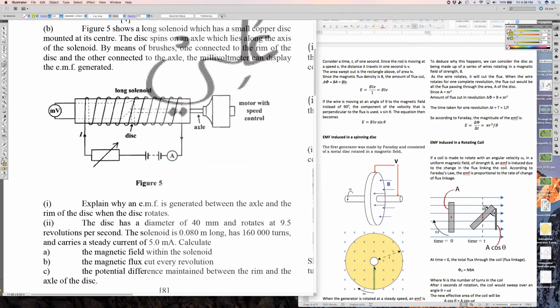This is an interesting question though. Somebody could argue and say, well, sir, this disk is really made up of a whole set of these same lines going around, so that's your N. And the answer is no, that's not the N, because when you make a connection, you make a connection from one point on the center to one point on the circumference, and therefore you've isolated one strand.